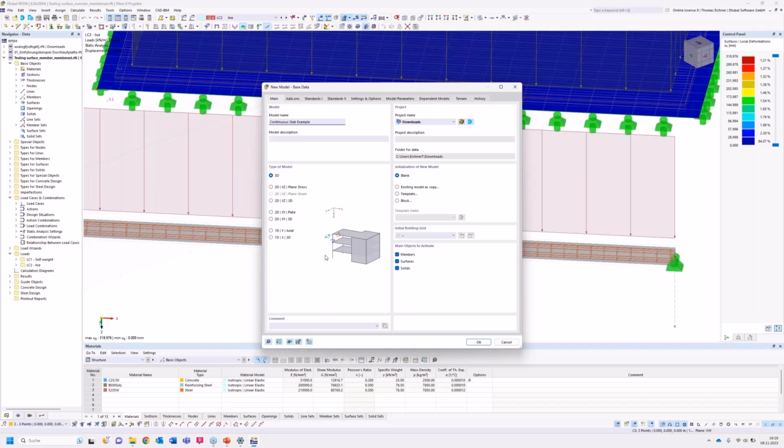Right in this 3D model, you see our 6 degrees of freedom. When we switch to our 2D plate model, we see it's simplified into just 3 degrees of freedom. Which means, for example, we don't have to define every support in the model. The program just supports the whole model in some directions, and that's what we're gonna use today. The 2D XY plate.